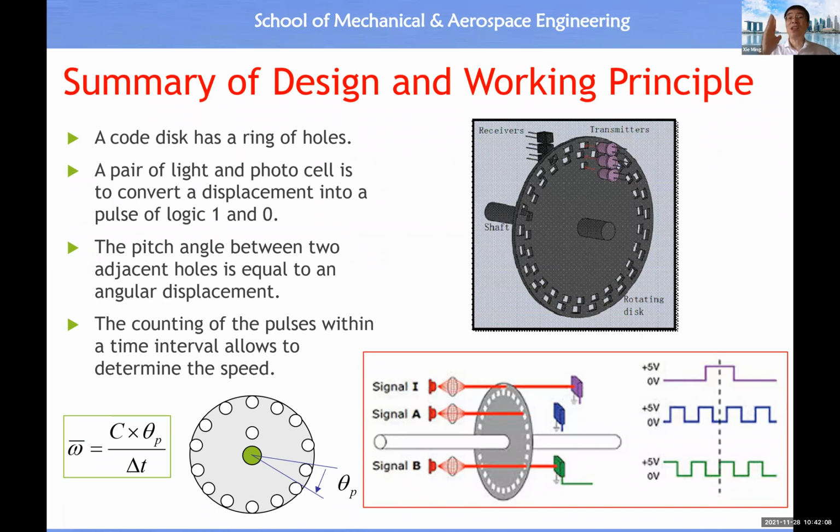Position sensor, we directly get the reading of the position. Okay, 10 degrees, 16 degrees, that's it. But for this one, we only know the displacement. Okay, displacement of 5 degrees. Then we want to know whether the 5 degrees is counterclockwise or clockwise. So therefore, we need to know this information about the direction of motion.